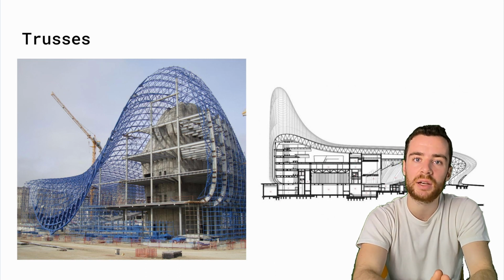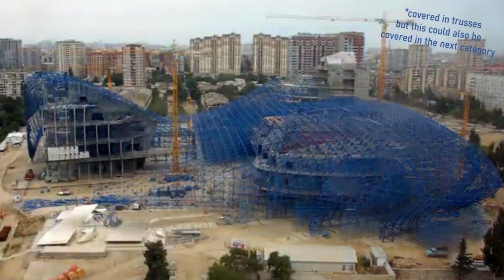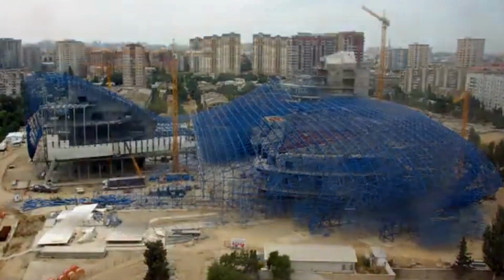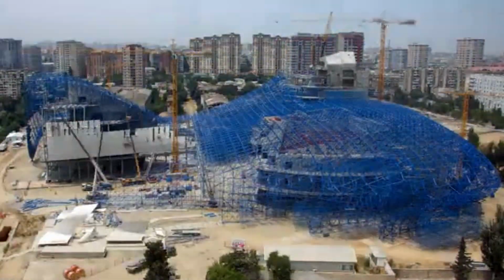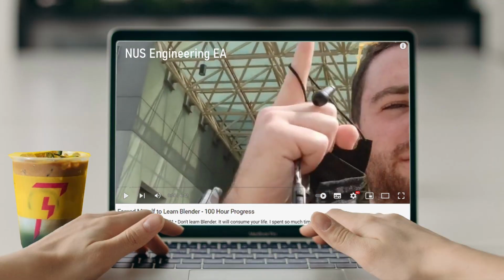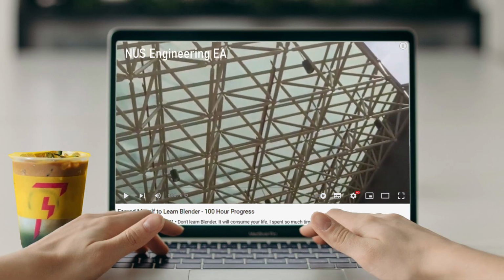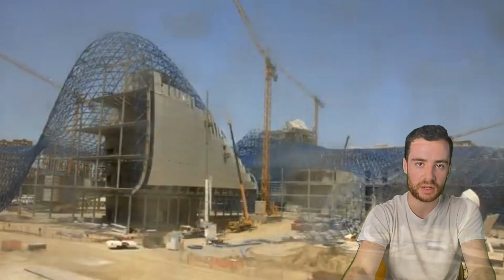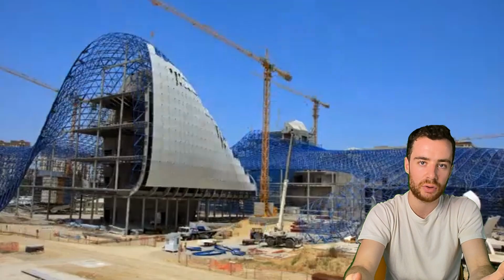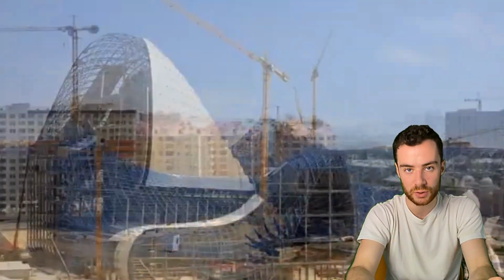Space frames being a lightweight, rigid roofing system where a series of connectors are joined together by chords or struts and with bracing members. Their strength derives from the rigidity of the triangle, with the flexing loads being transmitted as tension and compression loads along the length of each chord. Most space frames are constructed using structural steel or aluminum alloy tubes.